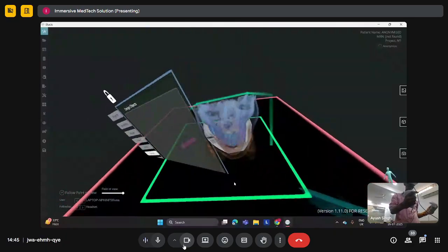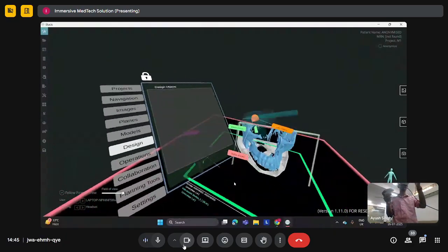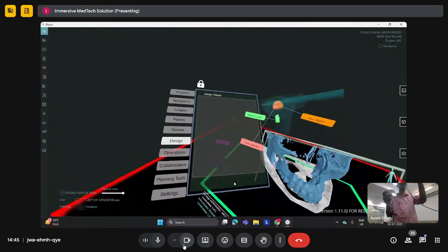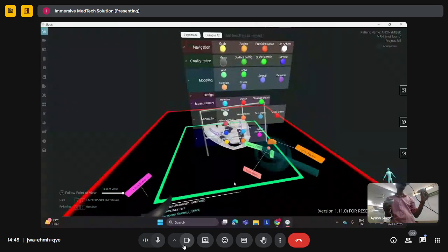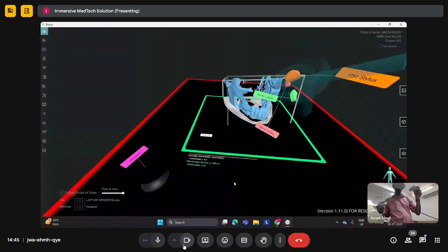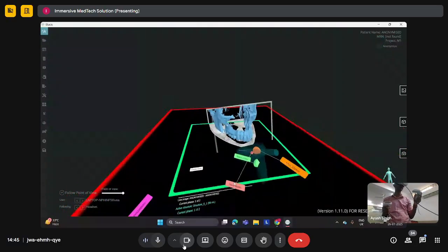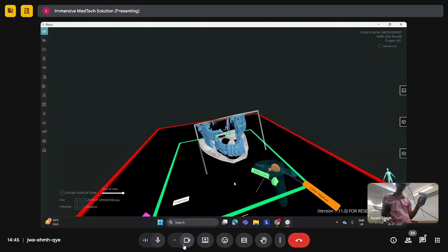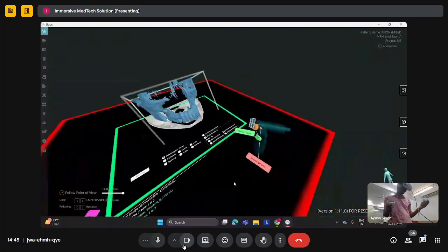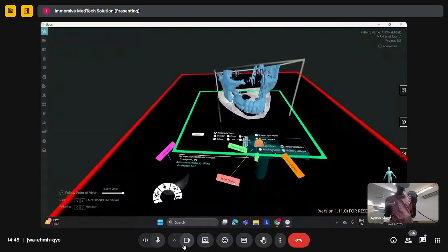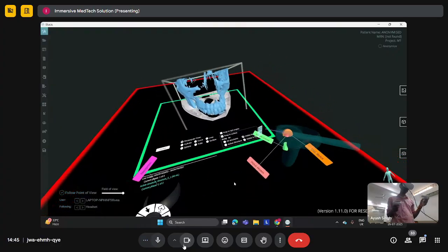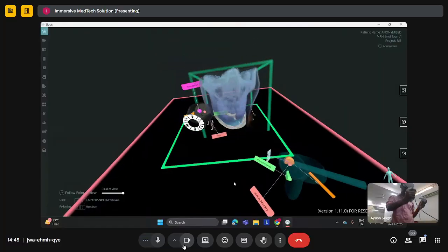What this particular design tool does is it gives us a freehand operation. So if you want to design, we can just go over here and click on edit. Here you can see in my view an option of create view. I'll just press that create view, and here we are given multiple options. We have a rectangular prism, cylinder, curve, cube, loop, and circle that we can directly model.